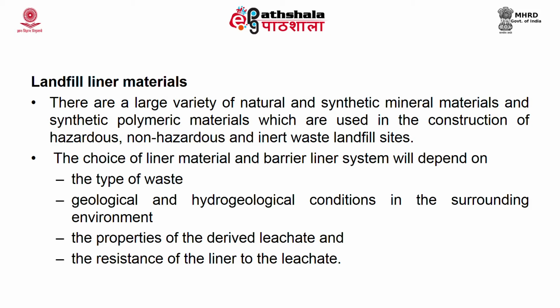One, your type of waste. For example, if you are talking about hazardous waste, then you have to choose a material accordingly because it should be more secure, and if you are talking about inert waste, a very minimal liner material, even one having the highest permeability, can be used.